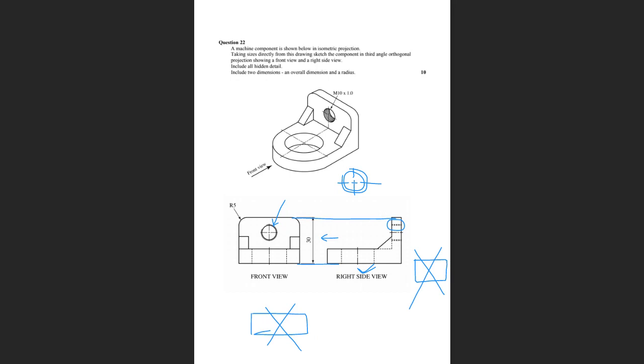The other problem is that some people showed the radius like this. Now, you don't show a radius for a hole, because that means the person that's manufacturing this has to do some mathematics to get a drill. So they have to multiply 10 by 2, and they could make a mistake. And so you're the draftsperson, you're the person that's drawing it.